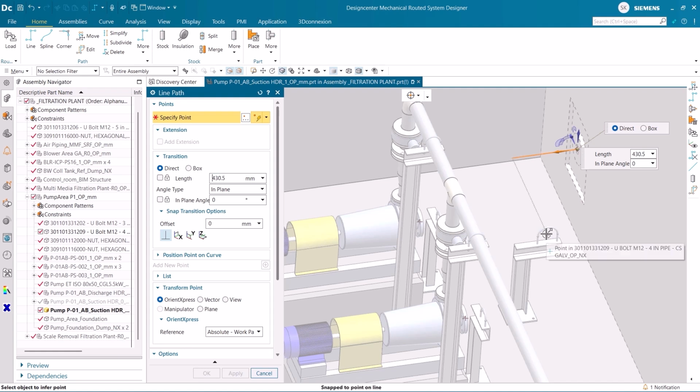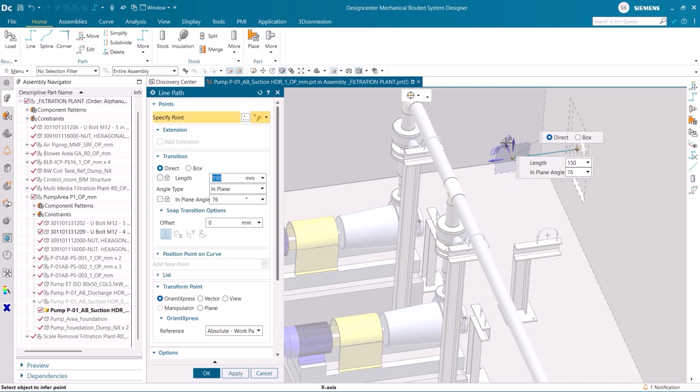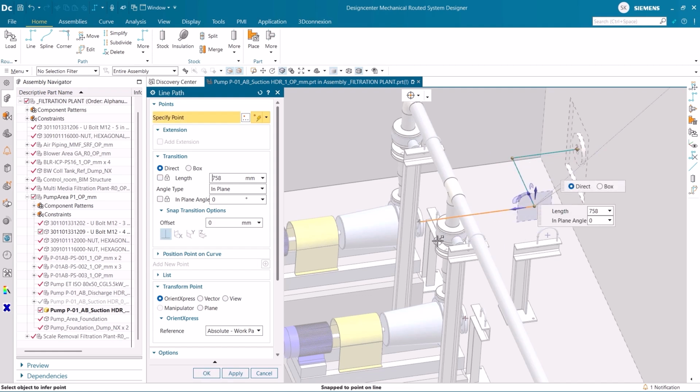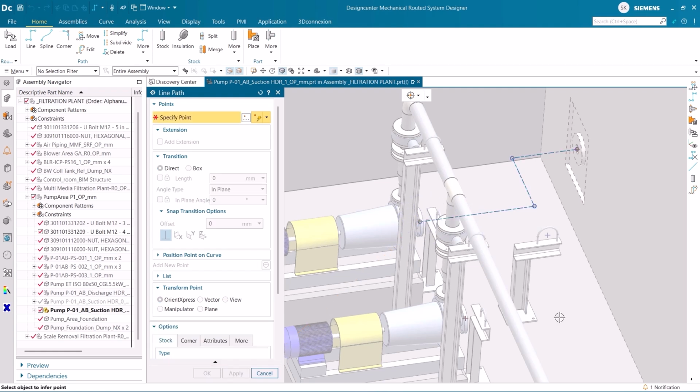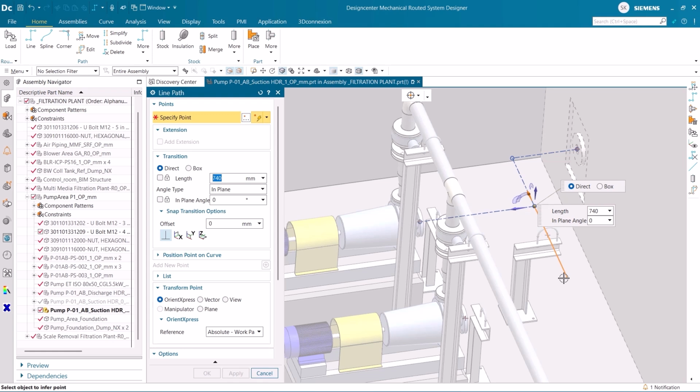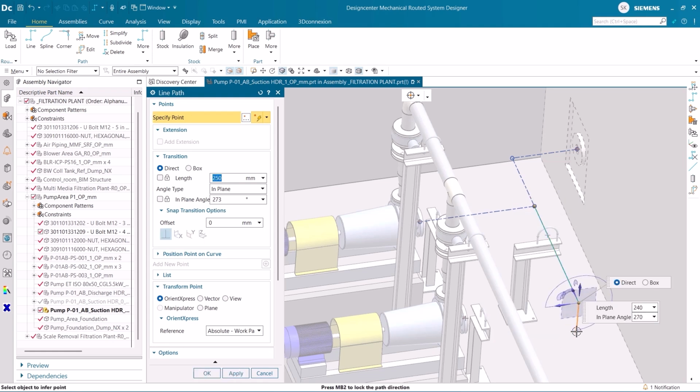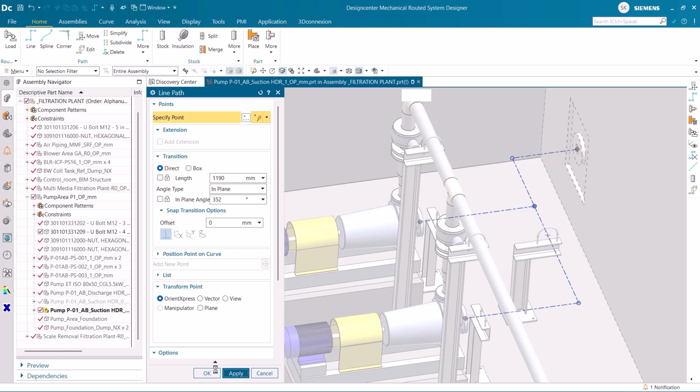Start with a path creation, then add components from the reuse library onto the path. Create the first path using RSD. I will add a second path to the second pump. Additional note, users can create a path and then break the path at a specified location or length to achieve the same type of results.